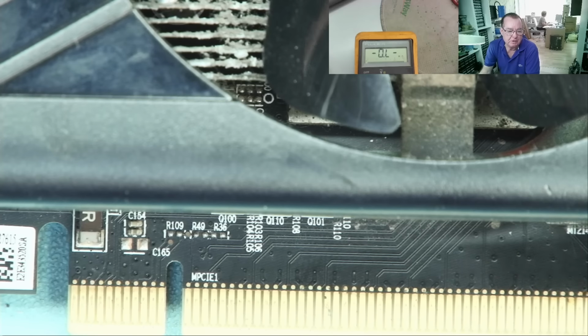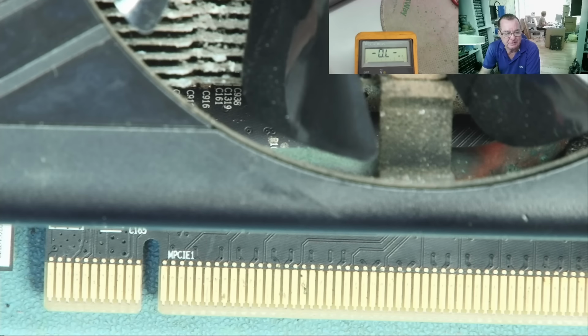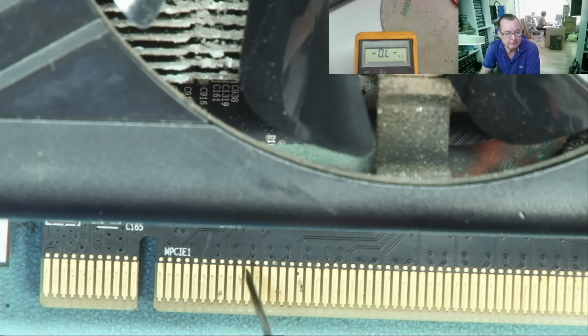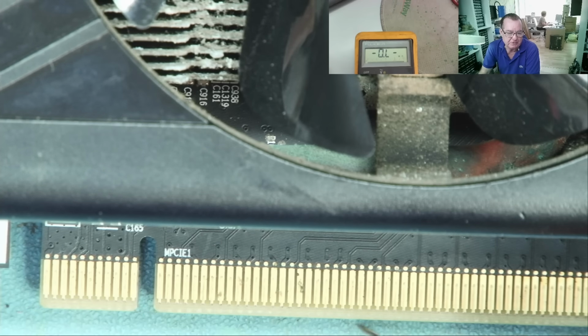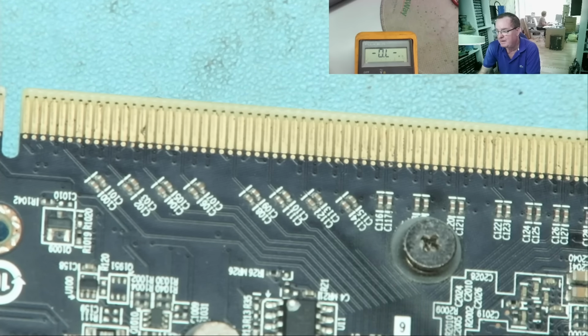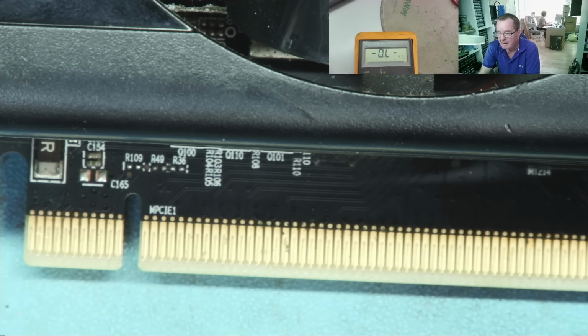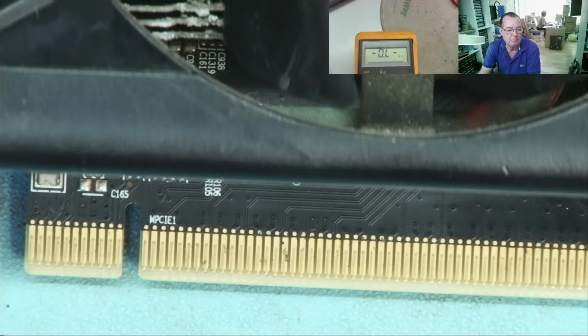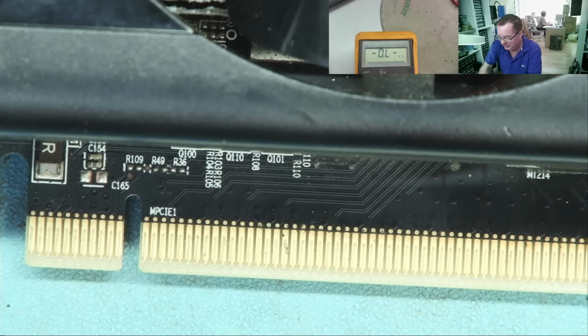Okay, so we know there's capacitors on one side of the graphics card and not on the other for the PCIe. That matters because what that basically means is that the side of the graphics card, these lanes which don't have capacitors on the graphics card, are more susceptible to damage, okay? On this side, the capacitors effectively isolate the connector from here. And the reason for damage is normally caused because you use a mining adapter and you put it in the wrong way round.